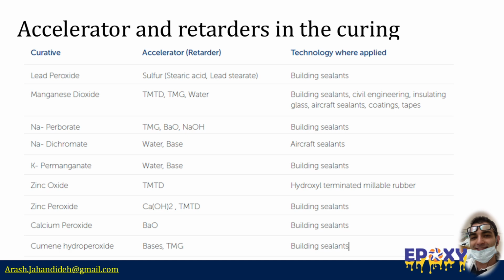A notable advantage of activated manganese dioxide or MnO2 is its relative insensitivity to the exact mixing ratio, offering robustness in formulation and processing. Water plays a crucial catalytic role in the oxidative curing of thiol groups, particularly with activated MnO2. The curing rate increases not only with initial water content but also due to the water released during the reaction, creating a form of autocatalytic behavior.